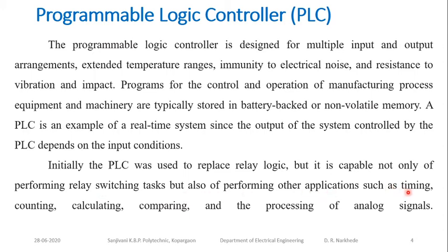So if I want to start a certain system after 10 minutes, 10 hours, or whatever, we can just use the timing function, from milliseconds, microseconds to a few hours, few days, few months also. So that timing function is there. Counting function: if I want to count certain events, how many times an event is going to be triggered, that is also possible. Calculation purposes also I can use the PLC.